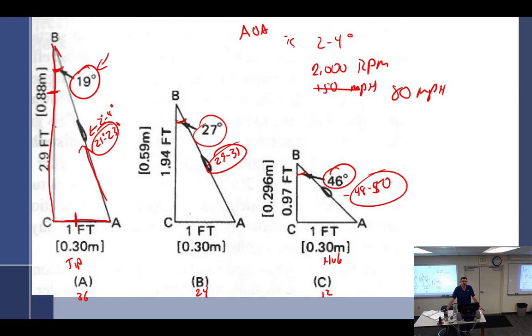Well, okay, let's say we take an engine that is perfect. It's a 150 horse engine, and we put it on a dynamometer and tested it, and it's exactly 150 horsepower at the rated RPM. If I put a prop on it that has too much pitch, or the blade angle's too high, and I run it, RPM is going to be too low. If I flatten it out, then the RPM is going to be too high.